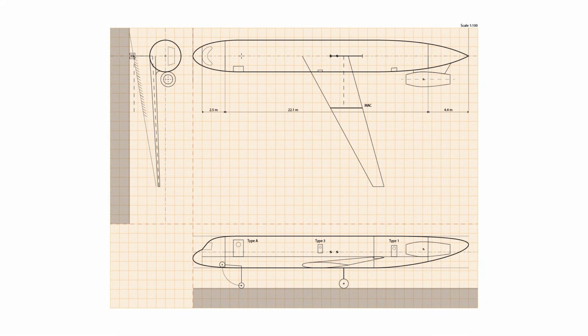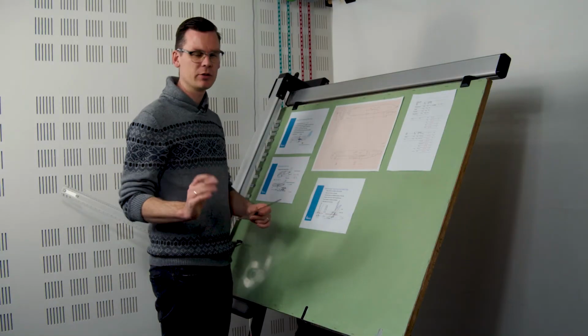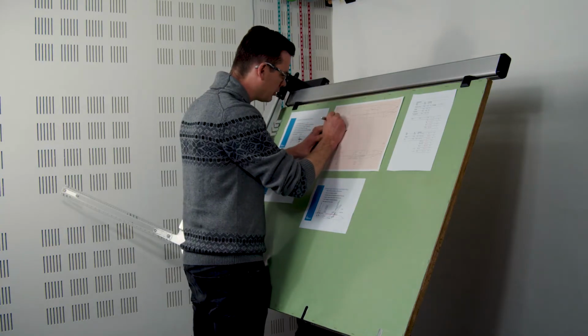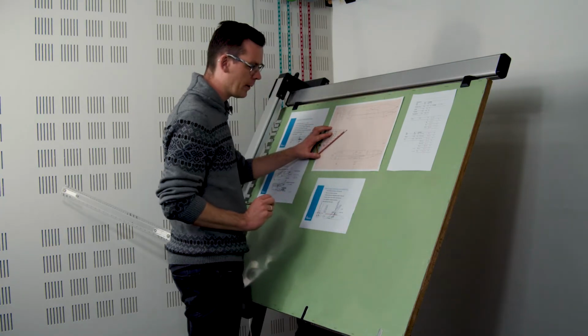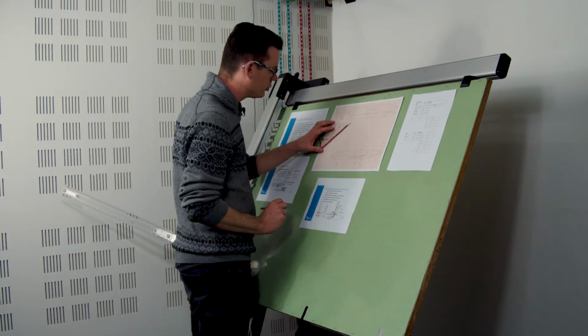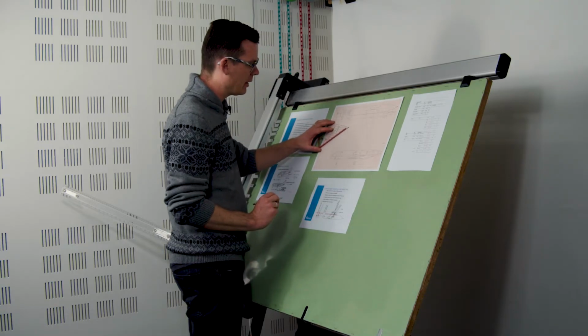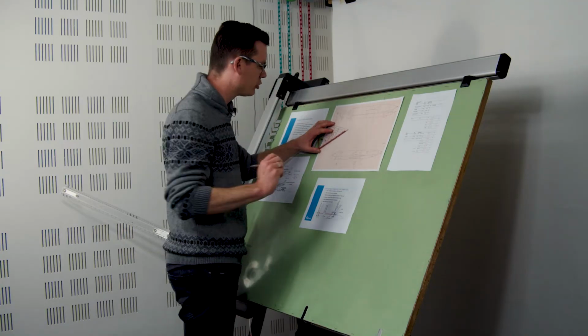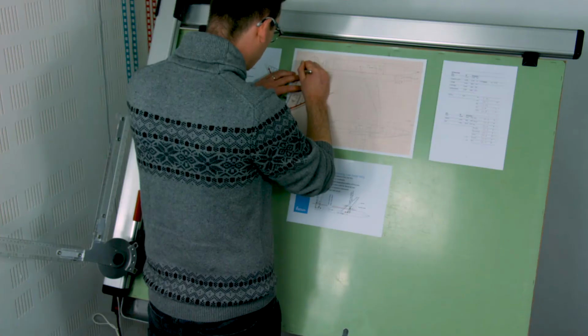So I'm drawing that constraint in here with the hashes indicating that the wheel needs to be to the right of that. Now, next point is at that intersection point between those two lines, so the axle and the constraint line, I'm actually drawing the middle point of the bogey.